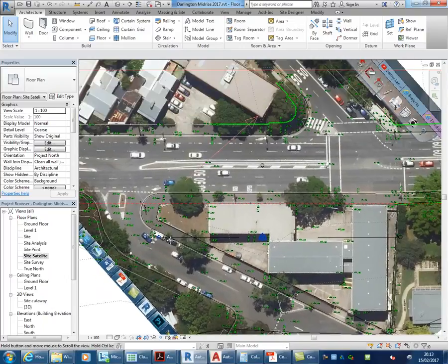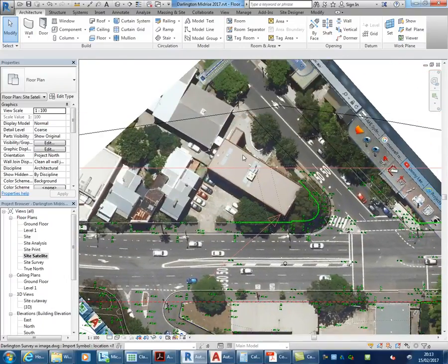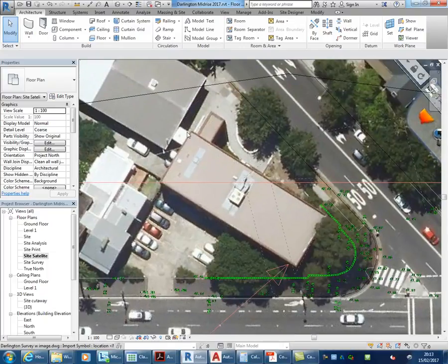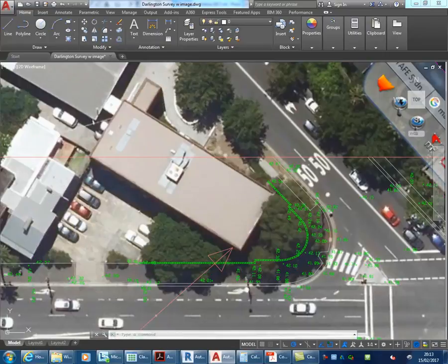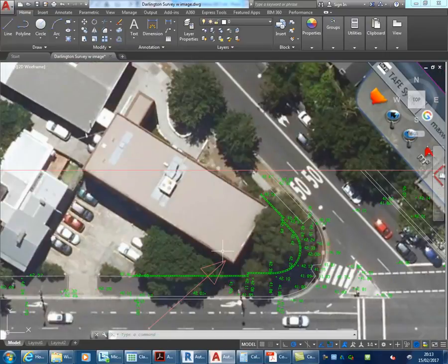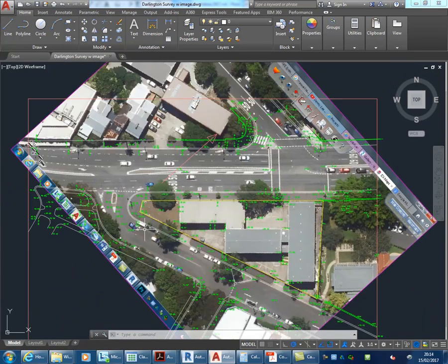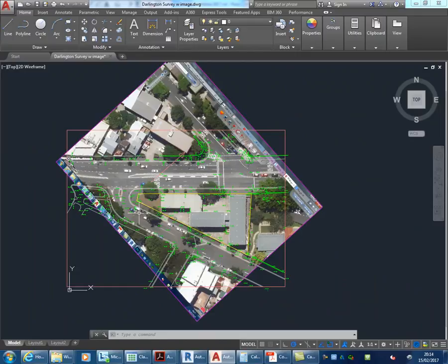So I've got a building up here. We want that building on our site analysis plan, definitely, and we probably want to get shadows from it as well. You could do the lines back in AutoCAD, and if I was doing this myself, to be honest, that is what I'd do. I'd draw all the lines, the outlines for the buildings, and then update the link into Revit, and then I can just pick the lines to generate those as solids in Revit.